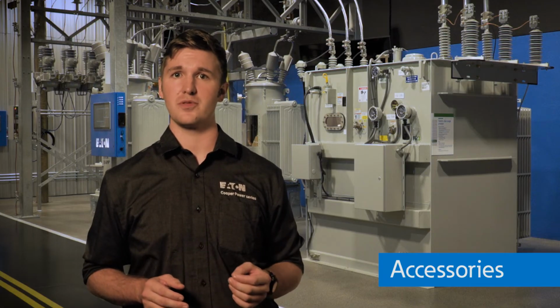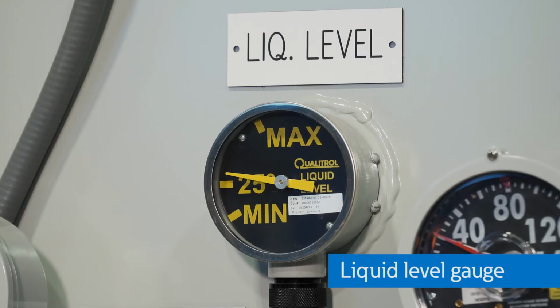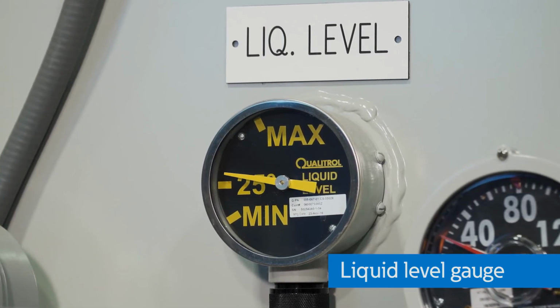3-phase pad-mounted and substation transformers can be equipped with a variety of optional equipment. Most such accessories are factory installed and no field work is required to prepare them for operation. A liquid level indicator is provided to aid in the systematic inspection of the transformer under load. It consists of a float arm inside the tank, an indicating pointer, and a magnetic coupling between the two across a liquid-tight separation. Under normal operating conditions, the pointer should be between the low min and high max level markings.